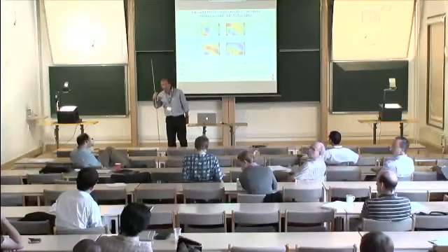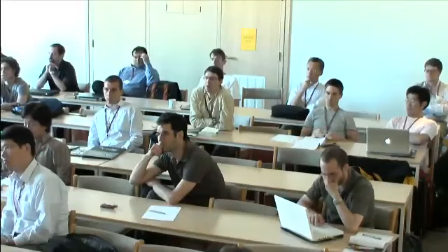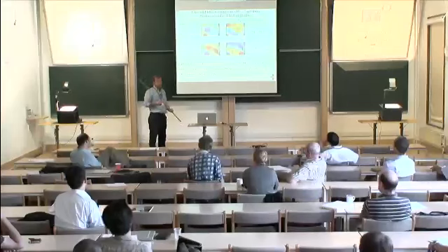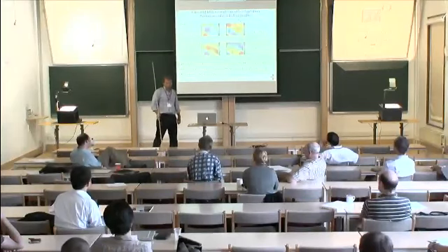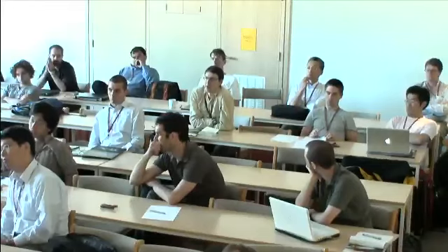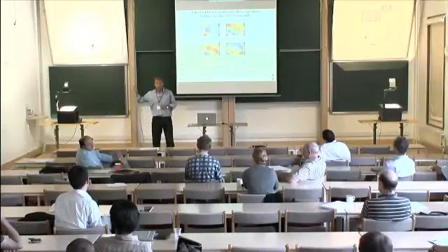In the 2D plot of the Mach number there, did you use a local sound speed and temperature to calculate the Mach number? Yes. This is why it takes a long time, because it's calculated local in time and space. So even the temperature perturbation. So is the perturbation in the Mach number due to the temperature perturbation or a natural velocity growth? It's mostly due to the velocity.